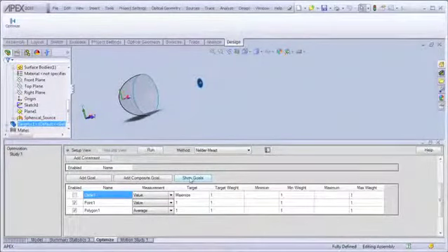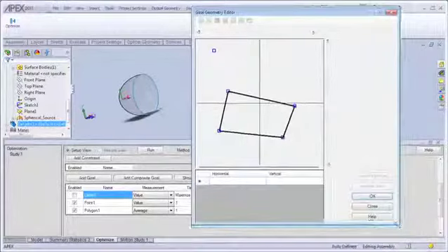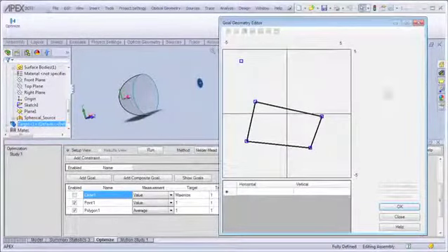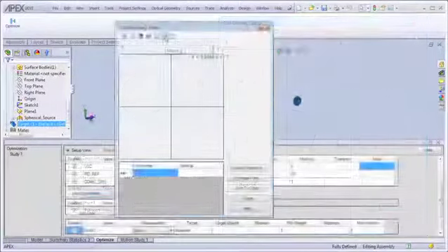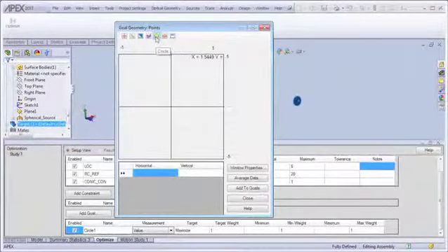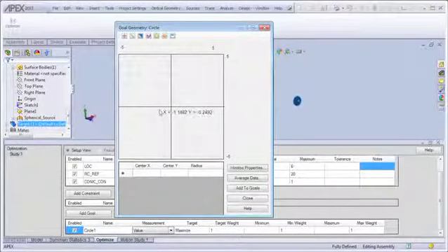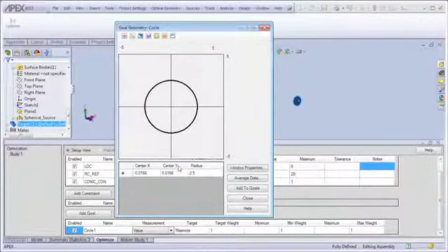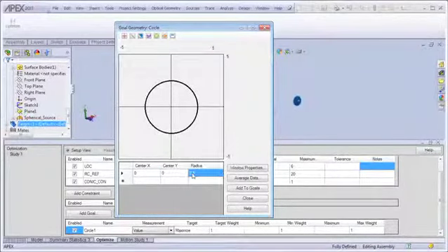These goals can be shown together. However, they must be of the same measurement type. That is, they must be of a power, irradiance, intensity, or radiance. In our particular example, we're going to designate a circle with the center and a radius with the center located at 0, 0, and a radius equal to the radius of the detector.